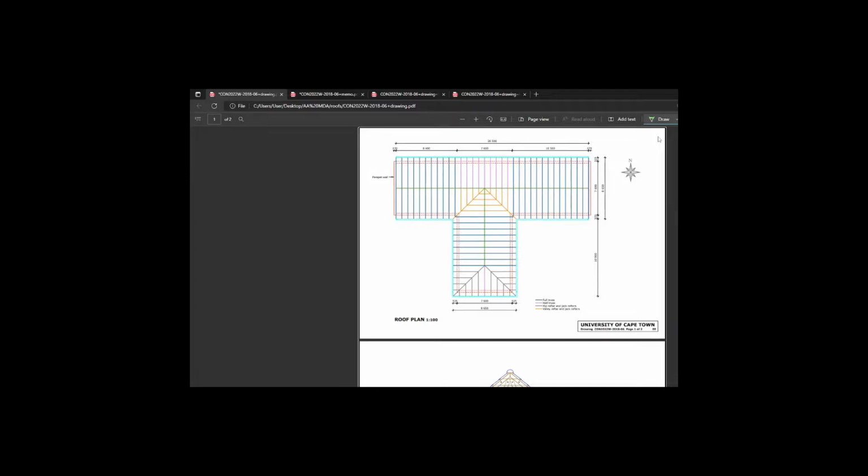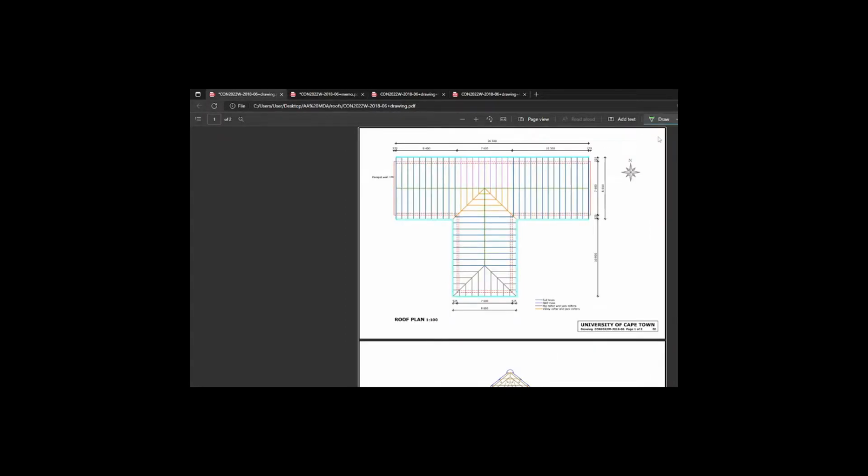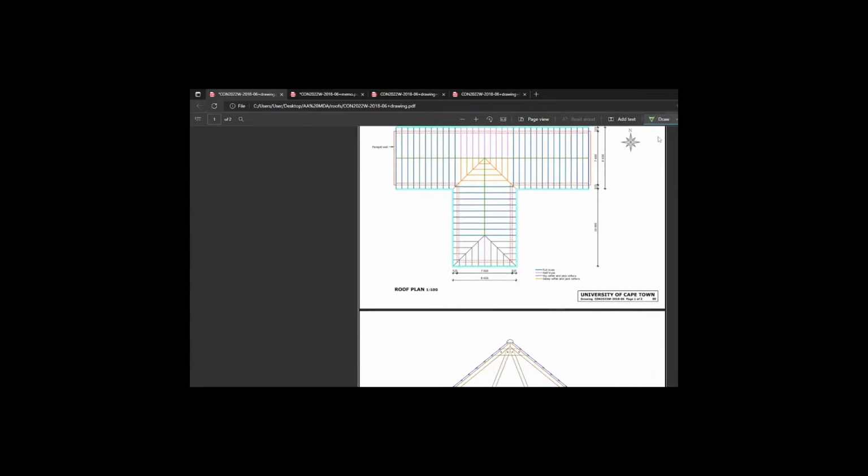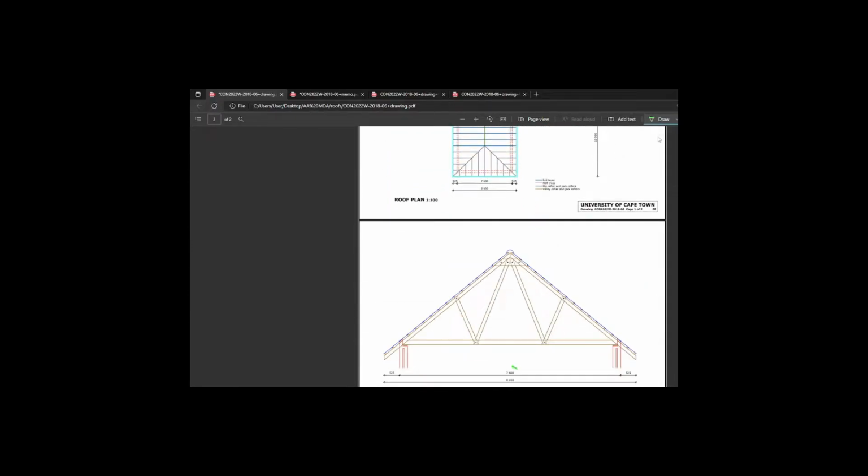7.38 is the dimension for our tie beam, right? Let's take a look here where 7.38 came from. Let's just go back here. Okay, it's not explained, but it was 7.6. Let's just drop it down here. There we go. So we've taken this dimension, 7.6. We've subtracted. You'll notice where it starts and ends. Sorry, the slide is a bit messy. Nope, made it worse. Okay, it starts and ends on the inside face of the outer skin.